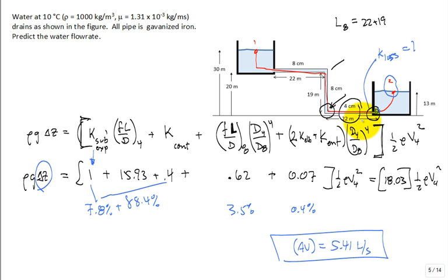You're just guesstimating on your 0.4 for your loss of that contraction, right? Well, that's the same 0.4 we used before. You have to read it off that chart. Yeah, because it would be 0.5, I guess, would be the ratio. I'll just say it would be lower, but it's trivial. Hold it. If you have a sudden expansion, 100% of that kinetic energy of the flow coming in is dissipated. And so all of it, so that loss coefficient's 1, not on the sudden contraction, but on the sudden expansion.